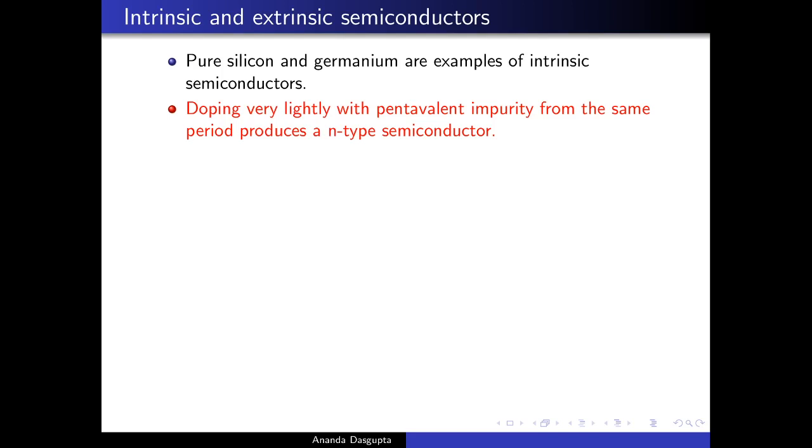in the original solid. If you have taken a pentavalent impurity atom from some other period, the size may be too big or too small. If it's too big, it may distort the crystal lattice and change the behavior. If it's too small, it may make the crystal lattice cave in. If it's like Goldilocks, not too big, not too small, just right, it sort of fits in right there. And if you remember your class 12 picture, it bonds with 4 of the neighboring atoms and has one electron free. In the band gap picture, you describe the same thing slightly differently.